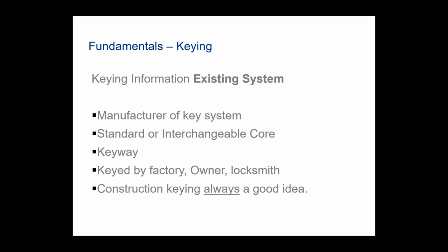Here it says construction keying is always a good idea. Absolutely, it's a good idea. There are some manufacturers that have very special construction type keying that goes in with their permanent cores, that you can have an in-construction key that you use, and as soon as the building is completed, the owner will take their permanent key, put it into that cylinder. As soon as they turn it, the key has now changed the configuration of how that lock is configured, and the construction key no longer works.